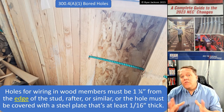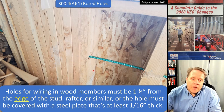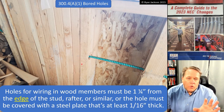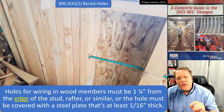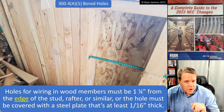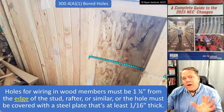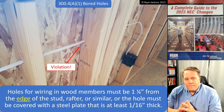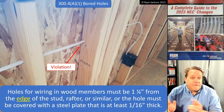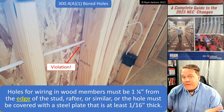And I think in most instances, that's probably not really going to make a difference. When we look at this picture here, is this wiring, where's the face of the stud? Well, I think the face of the stud is probably the part that we apply the drywall to. So it needs to be at least 1.25 inches from that, or we'd have to install a nail plate. But that's not my only concern. What about this hole in this location? Is that within 1.25 inches of the face of the stud? I don't know. It begs the question, what is the face of a stud?